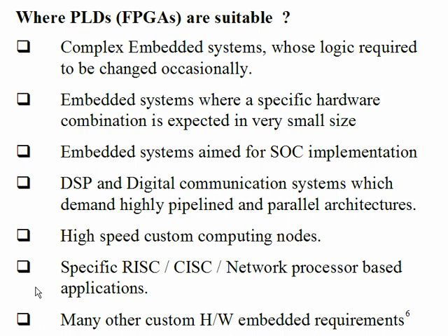That's the concept. Altogether, whatever I explained in different ways throughout the slides, ultimately the conclusions are very simple. Where is FPGA suitable? When I want to execute several things in parallel, which generally microprocessors cannot do, FPGA is the solution. When I want to reconfigure the system, where ASIC is very costly, FPGA can do this. Where I have a variety of combinations of hardware, CAN controller, bus controller and everything, and I want to get them in a single chip, the system on chip concept, FPGA can do the job. I told so many other things also, which we are not talking about now.